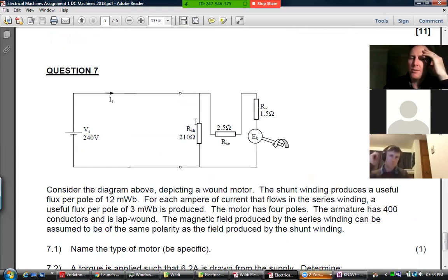You obviously don't want to group this one with it. No, that's just got a wee bit of current, because that's in the parallel. But these two, you can group them together. Or if you want, you can say there's a voltage drop here, IR across this one, and the voltage drop across there, IR across that one. But if you add those two, it'll be the same as if you took this one current and multiplied it by the sum of those two resistors, which is your series combination equivalent resistance anyway. So yes, they both cause a drop.